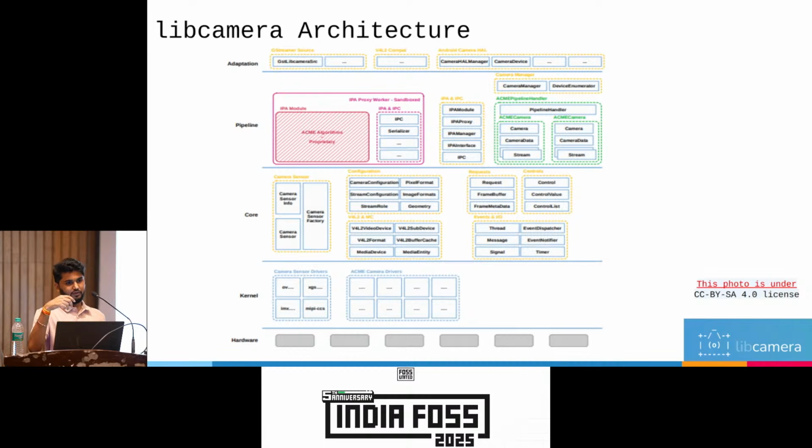Let's see, if you have the complex ISP I showed earlier, then the pipeline handler comes into play. If you have more than one ISP, the pipeline handler has an implementation of the different types of ISP you are going to support. There will be a match function that matches which ISPs your pipeline will handle. So in one Libcamera you can have more than one pipeline handler to handle these ISPs, and the pipeline handler also takes care of your stream configurations.